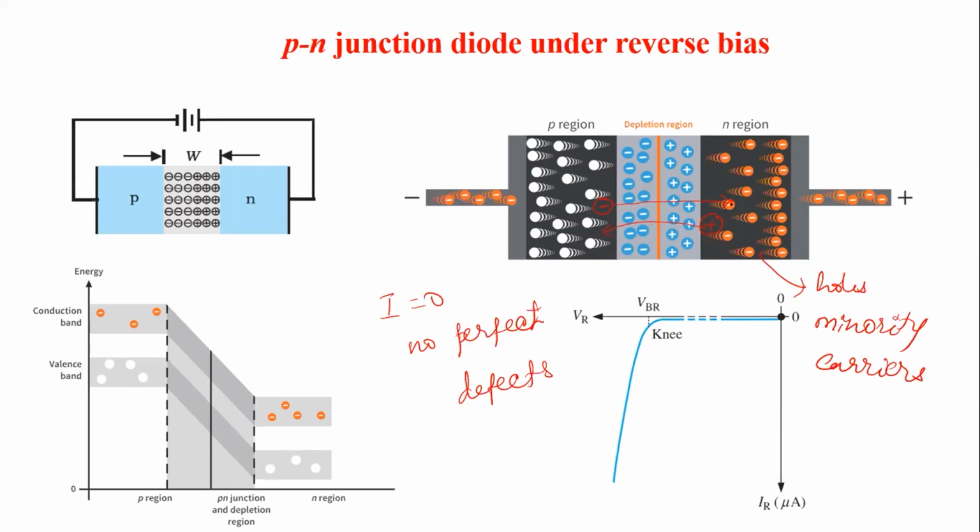They use this force to displace more electrons, and at that time we call it a breakdown. This breakdown can be of two types, Zener and avalanche. One electron hits another electron and frees it, then the two will hit and free four, and four will free eight, like 2 to the power n, it multiplies and goes on.